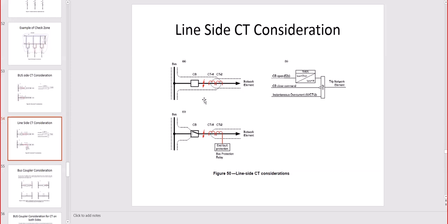So this is the IEEE standard where I extracted this. If you want to read the whole standard, it will be uploaded in the same spot on the PMC website. There is a limit for the non-synchronization between phases A, B, and C. They need to close with a maximum time delay between the fastest and the slowest of the three. Otherwise it's considered a fault.